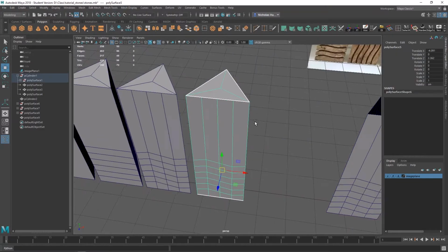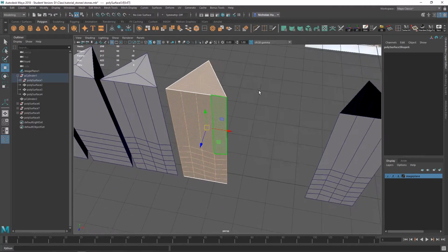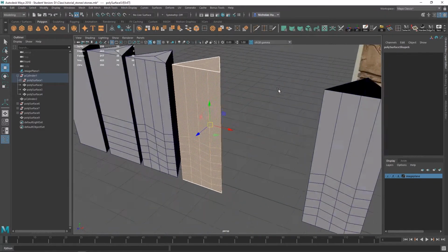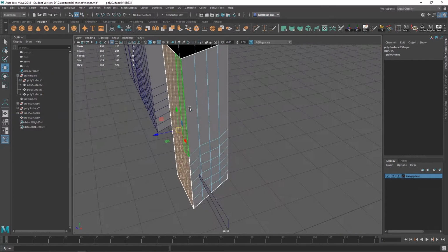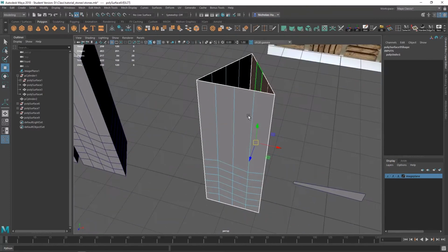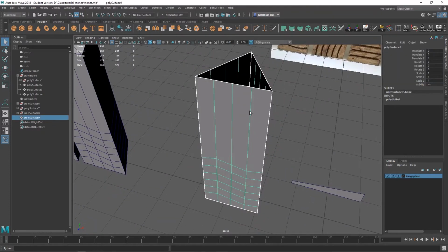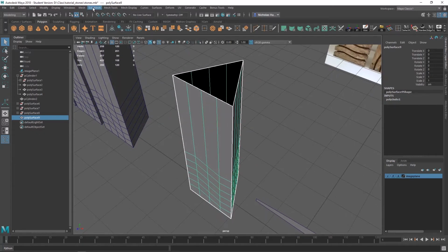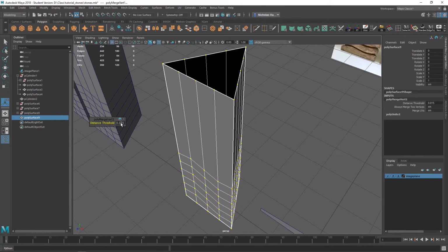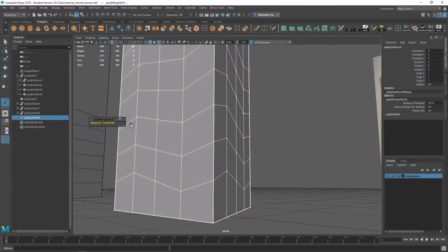So for example, if we go over here, go to face, double click, grabs the whole object because everything's welded together. If we come over here, because remember it was 3 separate pieces that we put together, we haven't welded it yet. So we want to weld that. So how we'll do that is we'll go into object mode, just select it in object mode, go to edit mesh, merge, and this distance threshold is any vertices within this distance of each other will be welded together.